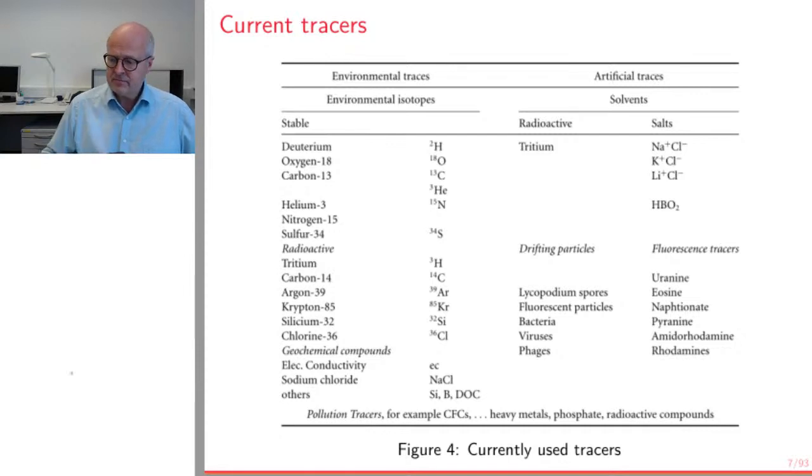However, this is an aquifer, so we have sediments with a porosity, and only 1/4 of that volume is actually filled with water. The rest is sediment. So instead of 800,000, I just have 1/4 of 800,000, which is 200,000.